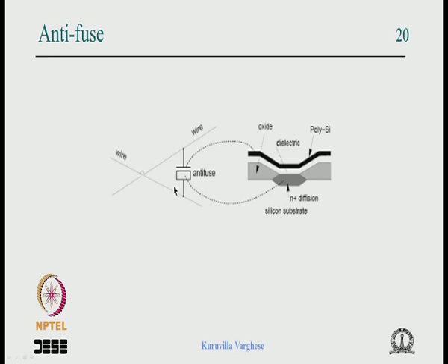Okay, so you cannot have the wires in the same layer as the transistor, so they are on a different layer, and the layer to layer connection is by drilling a hole, and normally on one layer the wires will run horizontally, in the next layer the wires will run vertically. Okay, because it's easy to interconnect, and also the coupling between the two tracks will be less, the capacitance between the tracks will be less.